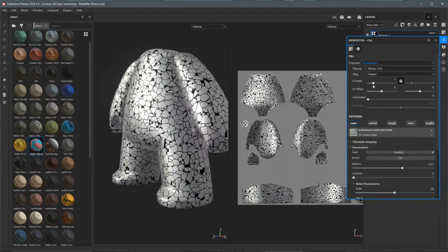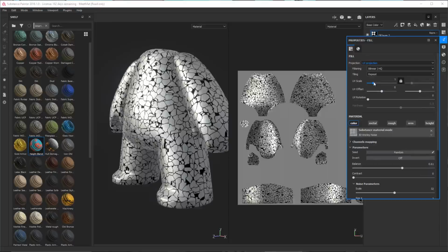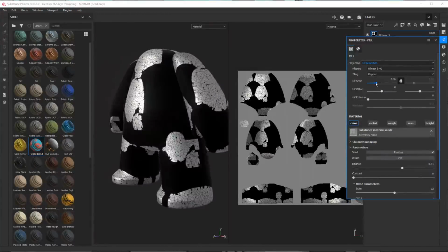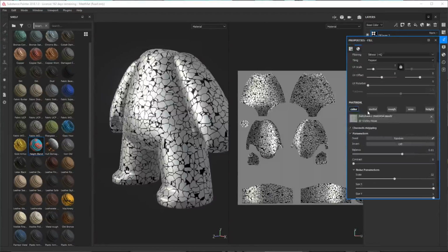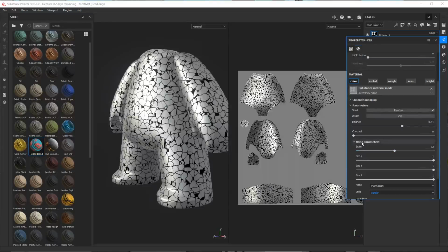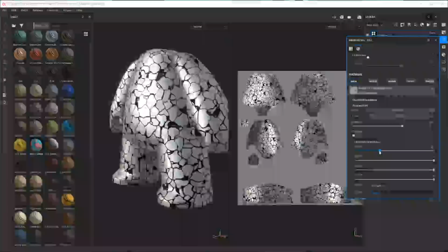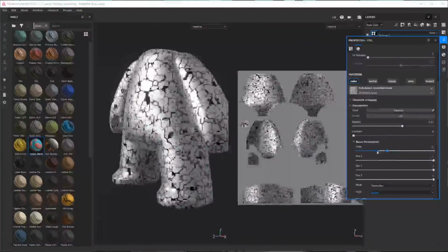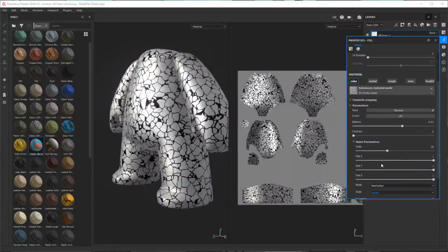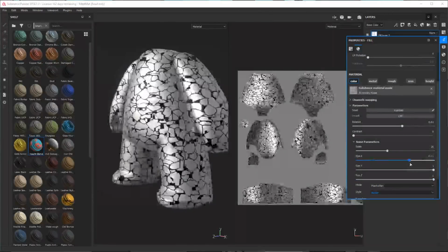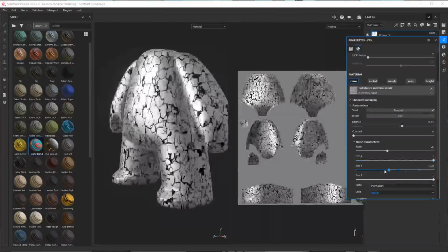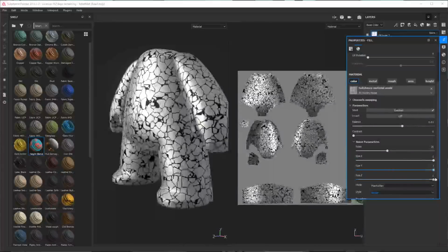Now, if you need to scale, again, here underneath the fill, you're not going to want to change the UV scale to do that, because the scale parameters are going to be controlled underneath these 3D noises like this. Here you have a scale setting, so this is where I can adjust the overall scale, but I can also choose to adjust scale on each axis. For example, we can change just the X-axis if we want, or the Y, or the Z. So we can break this off.